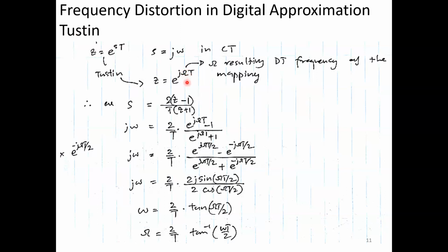So why do I use capital omega t? Because I don't know whether Tustin is mapping the frequencies without any distortion. Let's say if you use a 10 hertz signal into the Tustin to calculate the error integral, I don't know whether the same frequency is going there or is there any distortion. Now, in the sampler, maybe not a lot of people thought that it was actually doing this aliasing stuff, creating something totally out of non-existence into the system. So similarly, let's put a different symbol there for the frequency, that is capital omega.